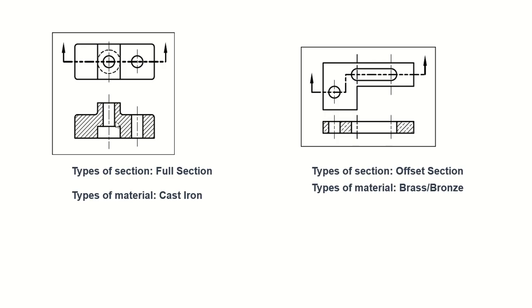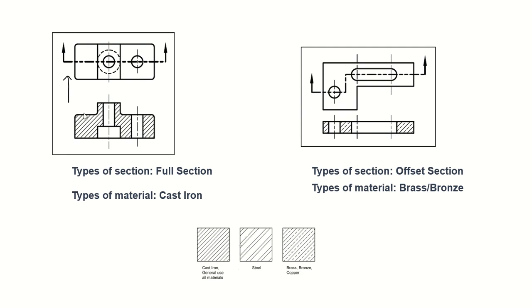Then the next one, so when you take a look at it, we'll cut in this way. We're gonna keep this part, and your line of sight is like this, looking inside. So here hollow, so you have hollow and hollow. First circle, second circle right here. And your center, take all the lines out for the center, another center here. Take all the lines out, and here is your cylinder because you're looking that way. Your eyes right here, and the cut material. I keep giving you this so you can identify. See, that's your cast iron. The next one, so this is full section.